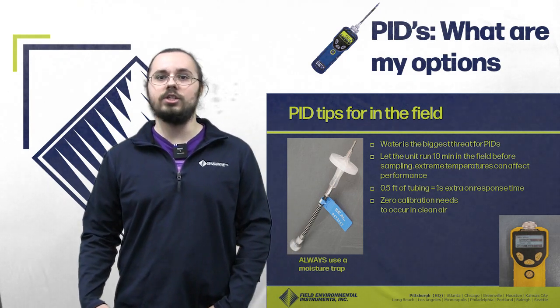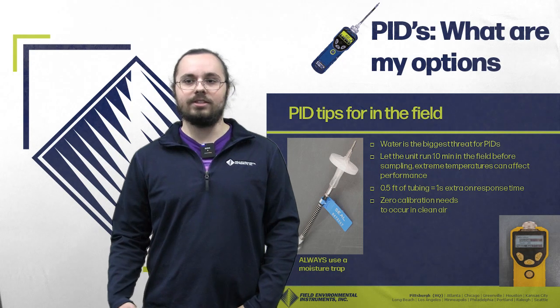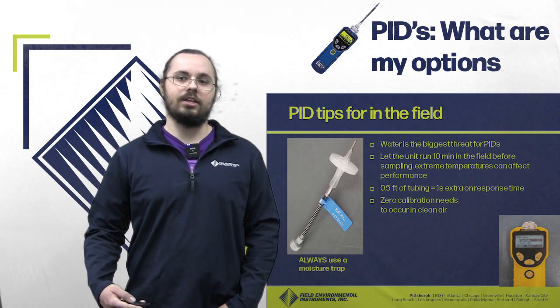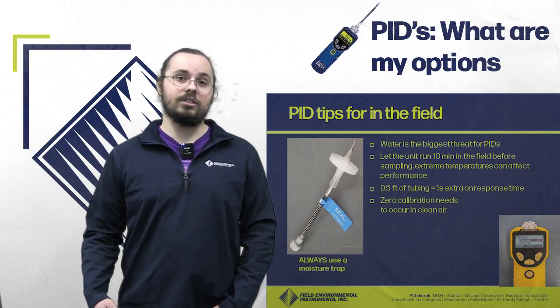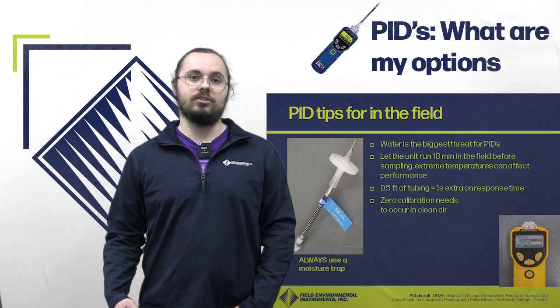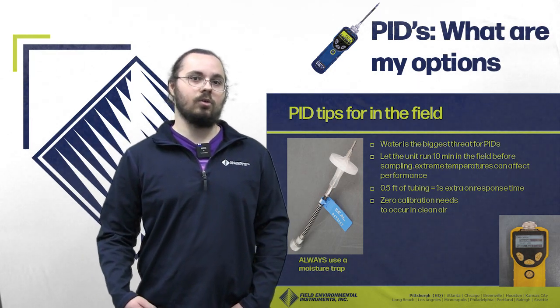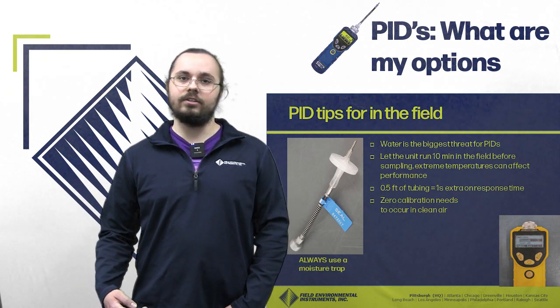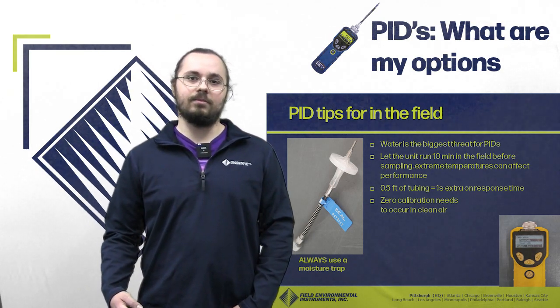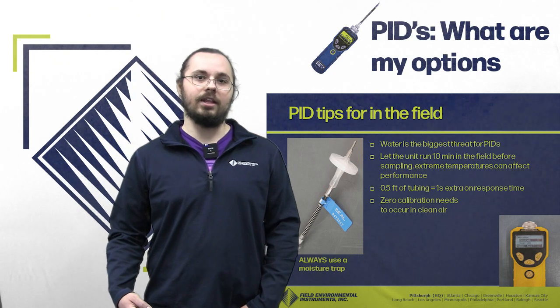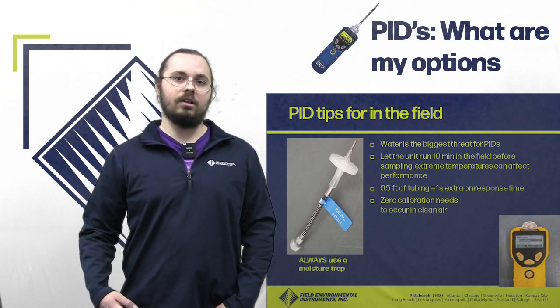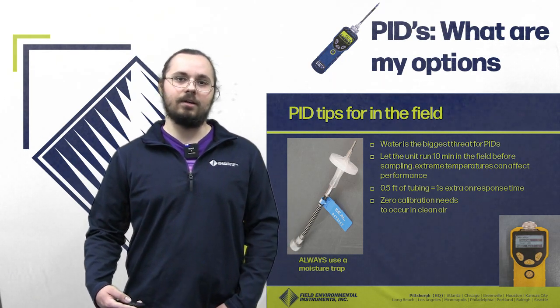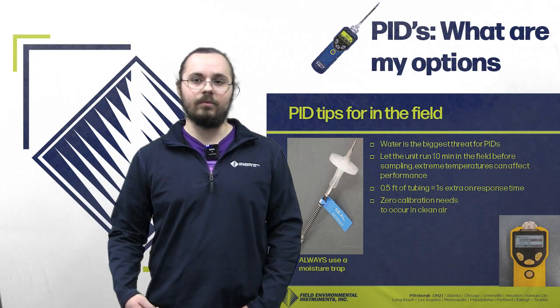Another important thing to do is to let the unit run for about 10 minutes before you actually go to take your samples. Temperatures can affect the performance of this unit, in particular extreme cold. So if you're in an environment where it's cold and you've been using the unit for a while, it's typically good practice to let it heat up, or put it in a warm environment to heat it up if it's been out in the cold for a while.